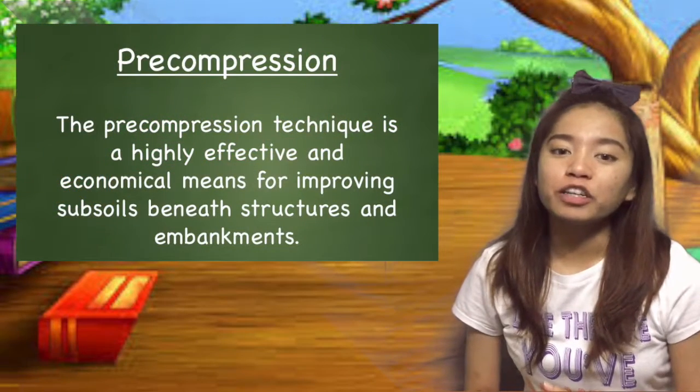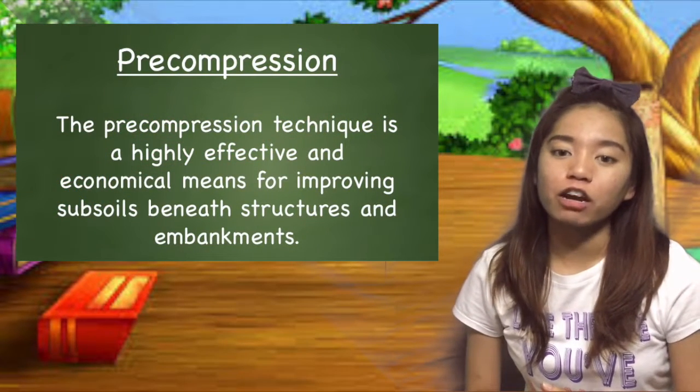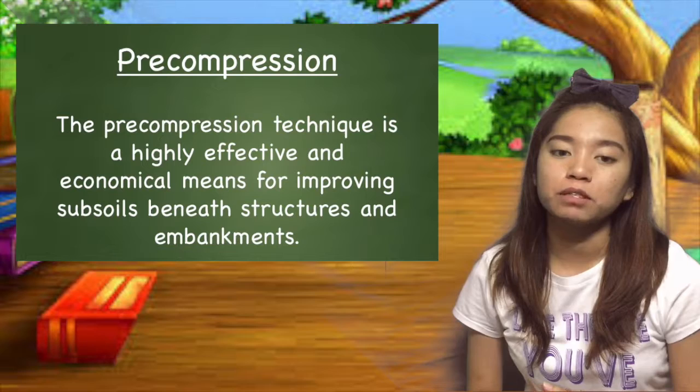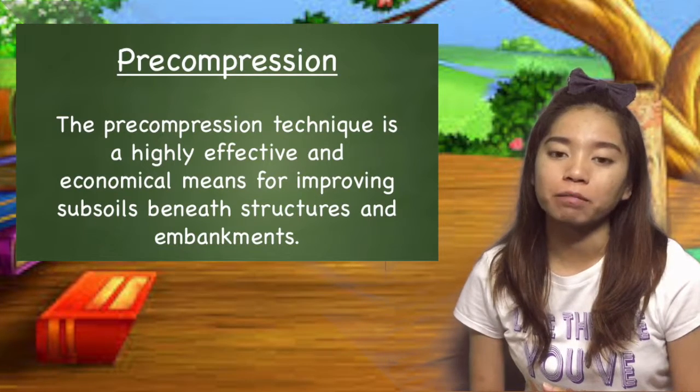Precompression. The precompression technique is a highly effective and economical means for improving subsoils beneath structures and embankments. However, it often requires considerable time, from months to a year or more, and its possible use must be anticipated during planning stages of a project. Precompression is not well suited where local concentrated loadings are high.